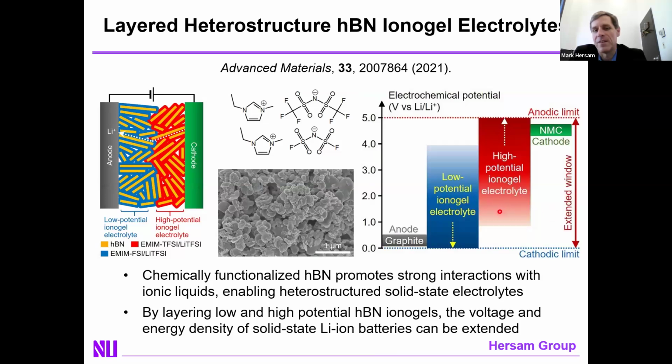The anode that everyone wants to use is graphite, because that's used in basically every battery today. So then you might say, well, change your ionic liquid to one that works at low potentials. And you can do that. The problem is that the low potential ionic liquid options are now limited in their high potential performance. And what matters ultimately in a battery is the delta V, the change in voltage. So both the low potential and high potential have the same delta V of 4 volts.